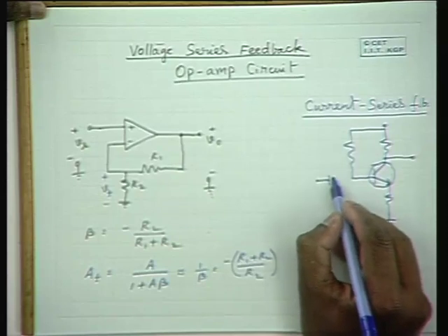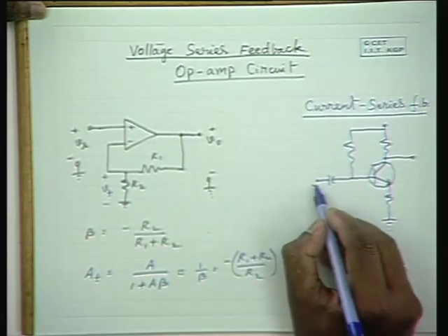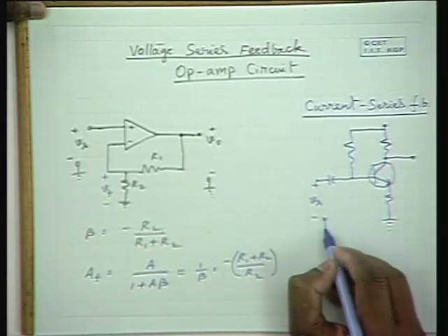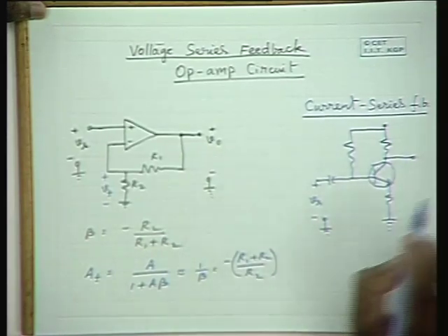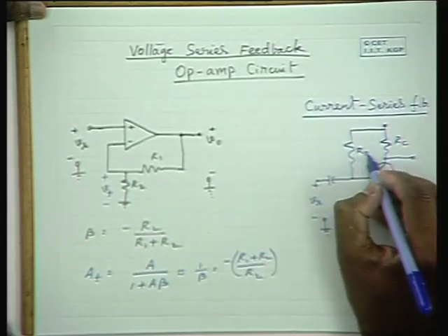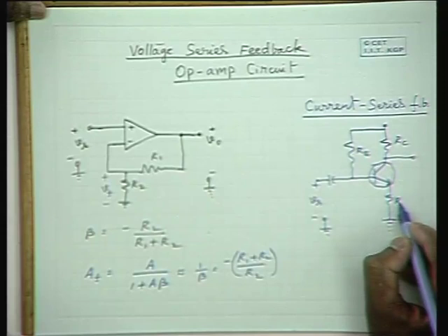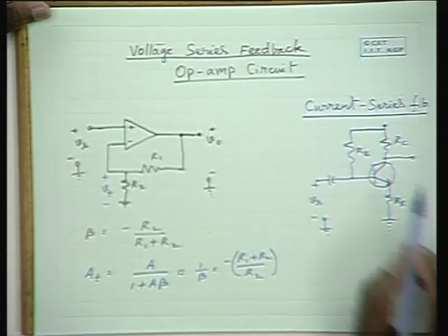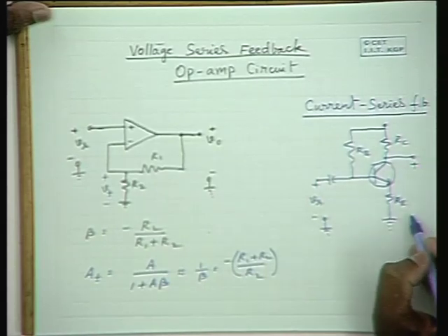This is the coupling capacitor to couple the input signal to the amplifier, and this is the output. And this is the collector resistance, as I mentioned, this is the biasing resistance, and this is Re, a feedback resistance. And this is the output voltage.